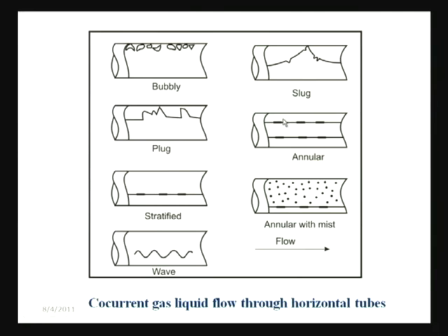And with gradual increasing of the liquid flow rate, we find that gradually the effect of gravity decreases, and more or less there is a uniform distribution. Okay. So, therefore, the moment we make the tube horizontal, by not doing anything else, we find that stratification sets in. So, we get 2 additional flow patterns, or in other words 1 additional flow pattern, that is the stratified flow. It is usually differentiated into 2 types, one is the smooth stratified flow, the other is the wavy stratified flow. Okay. Just because of the difference in the wave characteristics, some different treatment is necessary for the two, and therefore, we distinguish between the two.